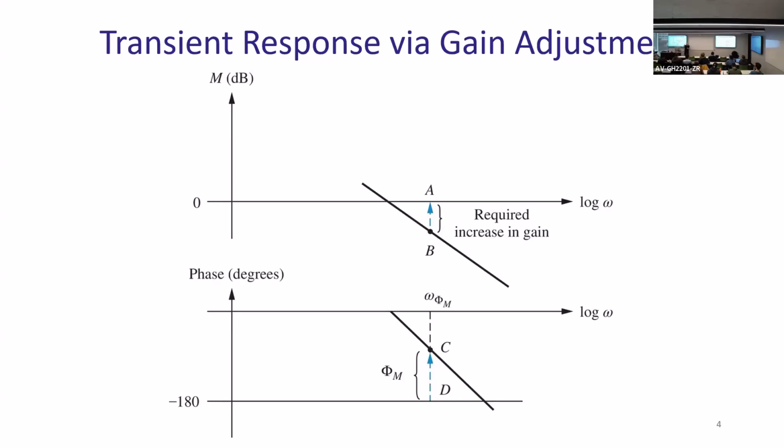We will just find a point on phase plot where you have sufficient phase margins that you want, and you can compute it from all kind of other things like overshoot, okay, zeta, and so on. So don't touch the phase, but play with the gain alone, and this gain will be crossing the 0 dB, which is gain of 1, exactly at the point where you have desired phase margin.